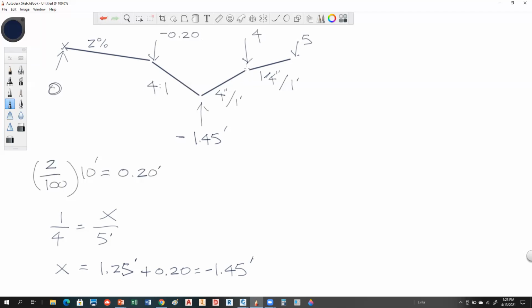Yep. That's going to make it really simple for me, because if I have to do this every 25 feet, I don't want to go back through and calculate all this stuff. All I need to know is what is the drop from here to here, or what is the drop from here to the center line, here to the center line, here to the center line. Because I can look on the profile and get this number real quickly. Is that making sense now?